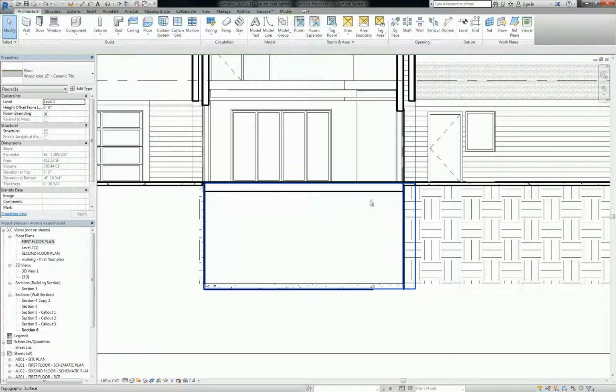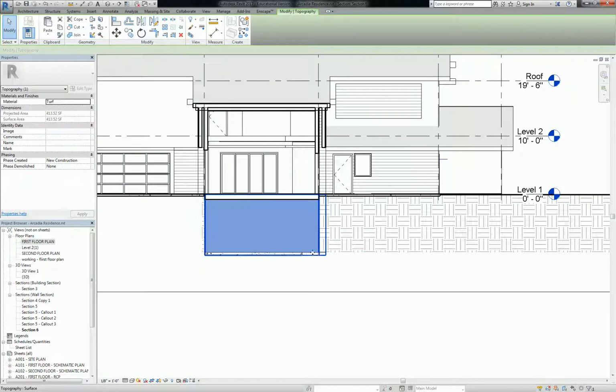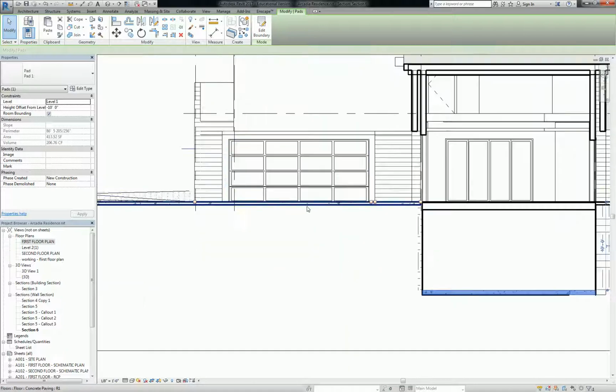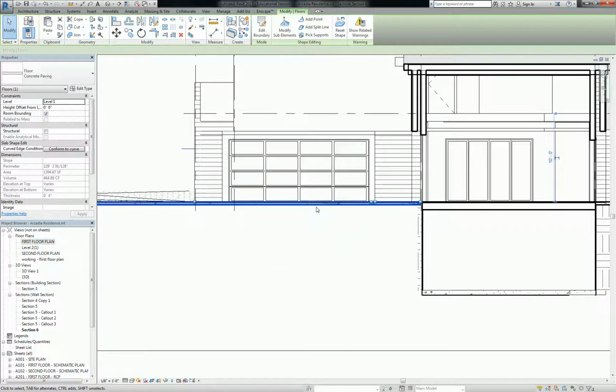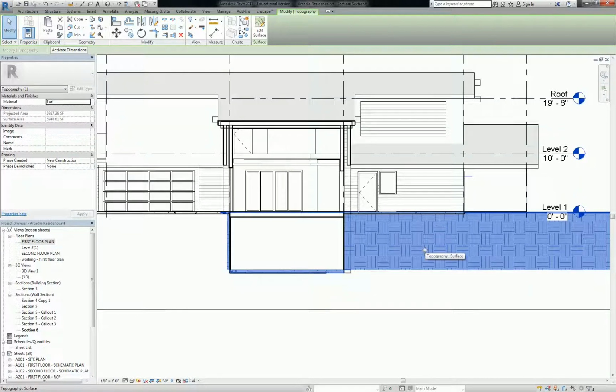something like that. Okay, so anyway, all I wanted to communicate to you was that you can use the pad element in order to create those voids in the topo surface. Otherwise, if you're going to be using a lot of the floor surfaces and stuff like that, then you're going to have to go back in and draw all of this earth hatch around the space, which isn't that big of a deal.